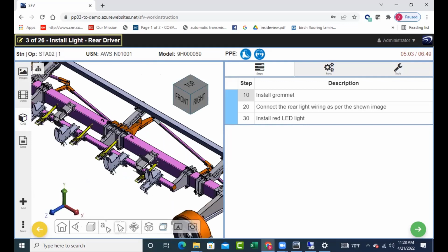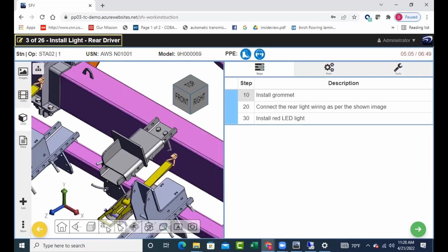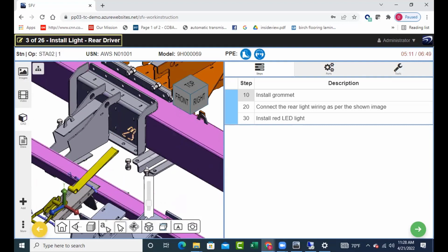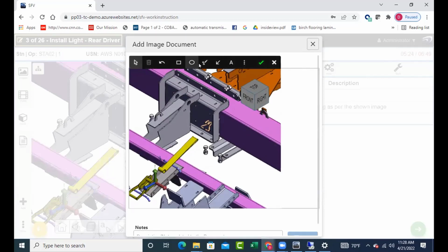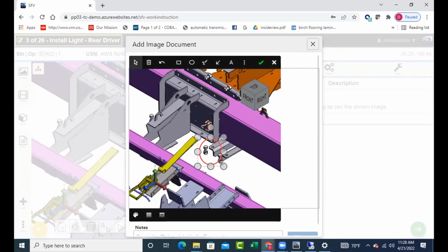So I could go down to a specific section of the CAD file, explode it, get down to my bolts and nuts. And then I could just do a markup here, just like I'm doing with the change request on the static image, right? Take a snapshot. I can annotate that snapshot, right? I can draw my circle wherever I want to. And I can now push this just like I did to the static image down to the shop. So this is another capability that's available now.